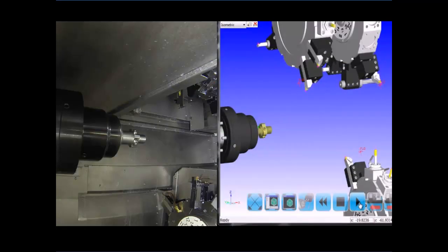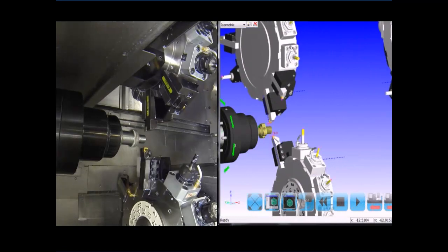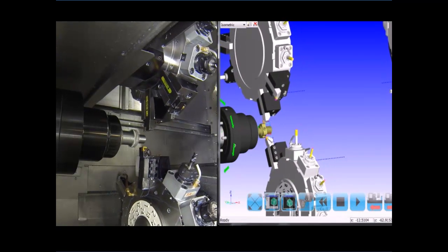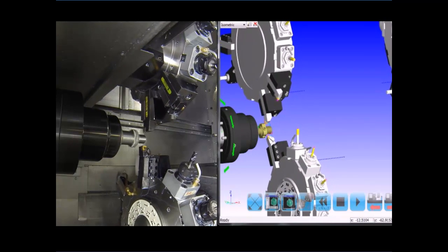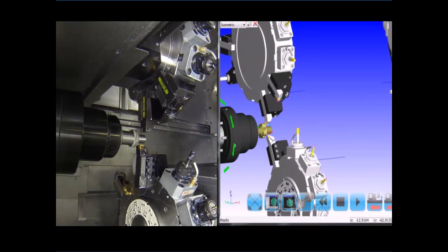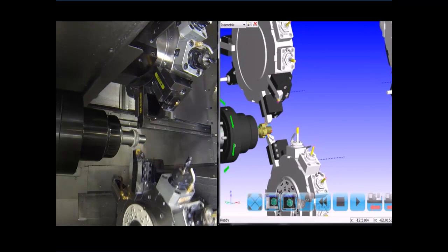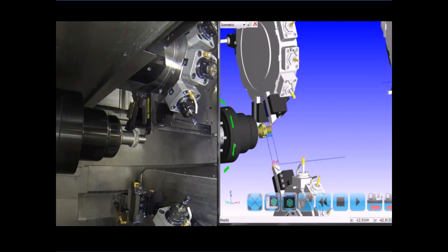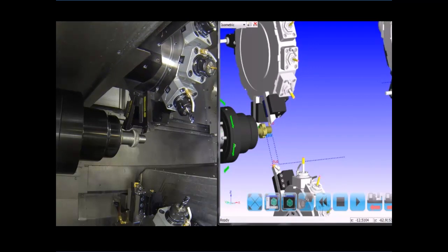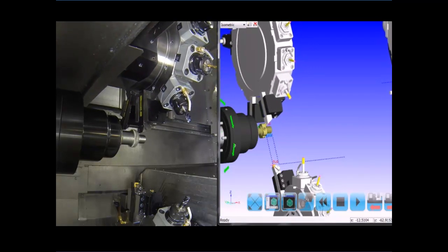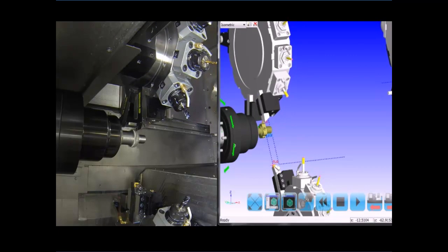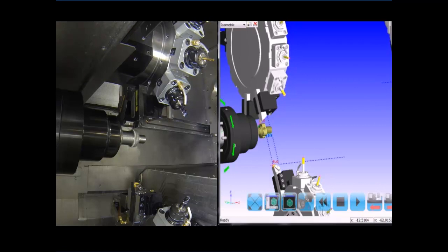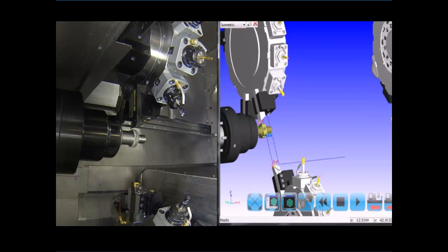In this particular slide, what you're going to see is the software running and the actual part being cut. The timing is not perfect, but it is very, very close. Normally, a complete project is within a couple of percent of the actual cycle time. Unlike typical CAM systems where it can give you a feed rate time, the rapids are never correct because they don't take into account accel and decel rates and turret indexing positions. You could literally program a job, get an estimated cycle time, and quote your work to a customer.